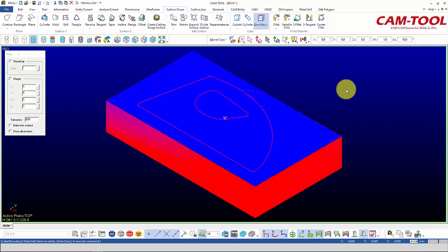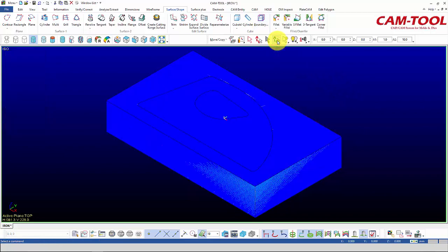Next, we are going to create a toolpath boundary to give our tools an area to work in when we create our programs. First, let's deselect everything by using the Select None command. We're going to create the boundary on layer 15. We can make layer 15 active by entering it here and then hitting the Enter key. To create this toolpath boundary, we're going to use the rectangle function. By making a rectangle and then selecting it as our toolpath boundary, this is what will define the area that our programs can work in.